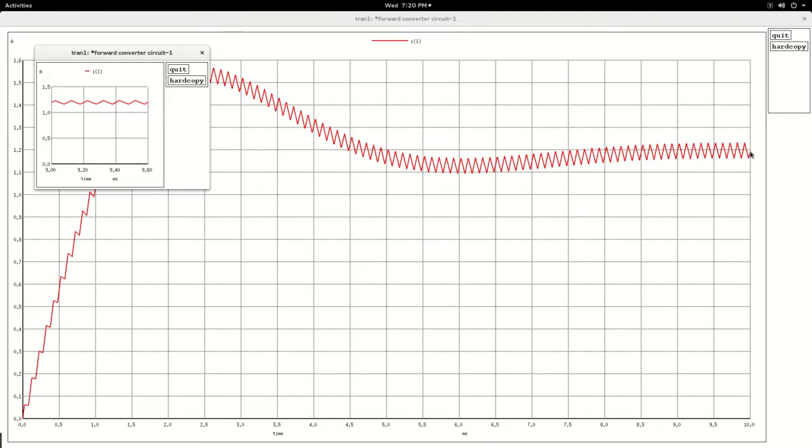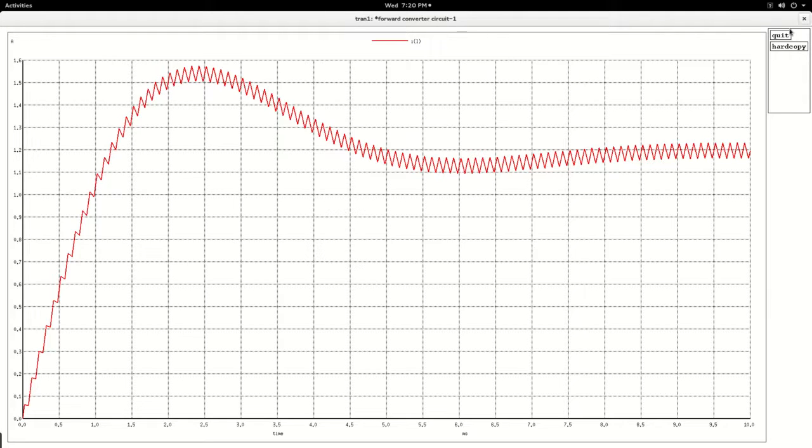You could probably give the initial condition at around this value, so that quickly you will see your circuit coming to a stable state from the initial condition. That is a very nice approach to shorten the simulation time if you are not interested in the transients.